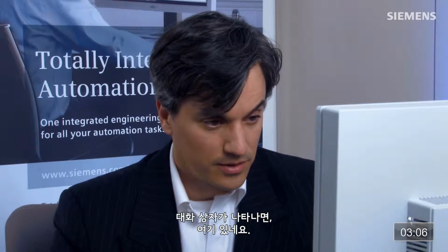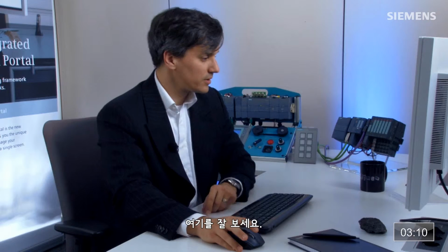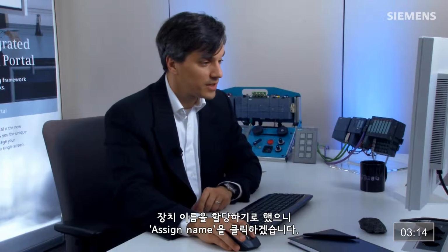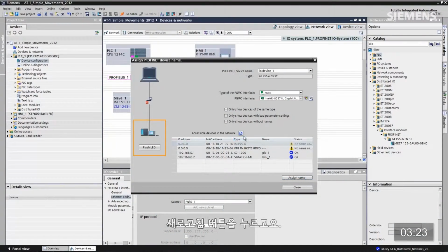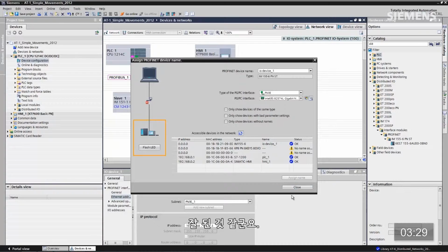And once we have it, here it is, we can actually assign the name. If we give focus to it, click on Flash LEDs. This is the correct rack that we want to assign a device name, so let's assign it. At this point, it's going to go out and scan the network again, try to find that hardware, and give it its device name. Then I can click on the refresh button. It will scan the network and make certain that it physically has been assigned. It appears as if that is correct.